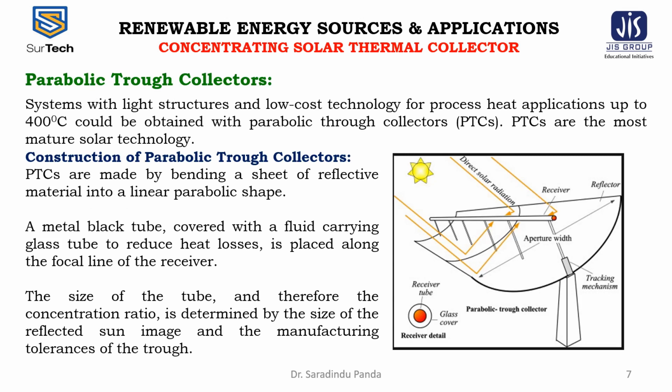Now come to the parabolic trough collectors. In order to deliver the high temperatures with good efficiency, a high performance solar collector is required. The parabolic trough collectors can effectively produce the heat at the temperatures between the 50 and the 400 degrees centigrade as well.